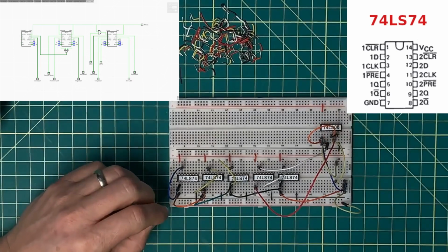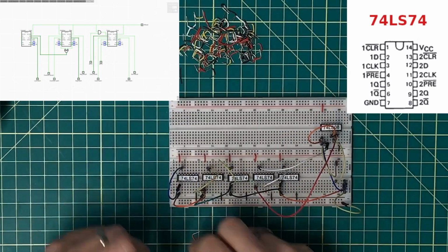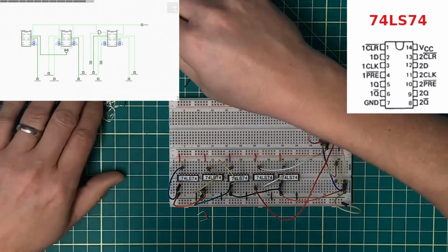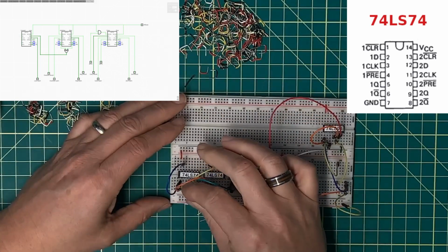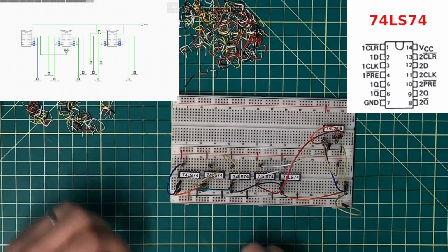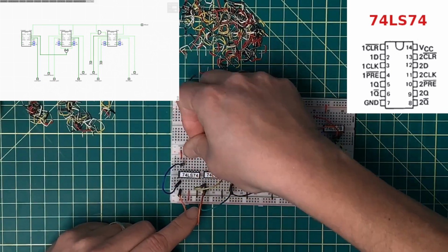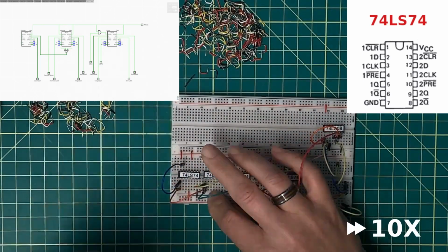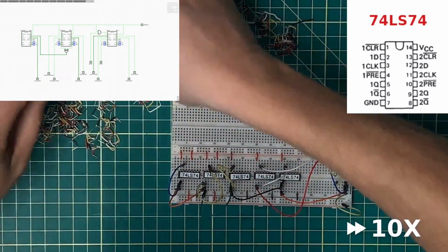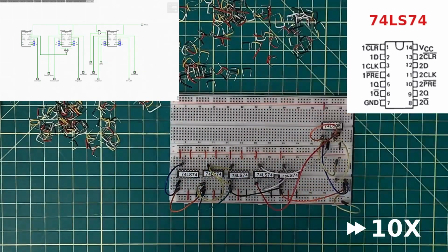Sets are all going to be tied. Let's see, that's pin 4 and pin 10. These are all going to be tied high. And I need some longer wires here. So pin 4 and pin 10. And so the key with the sets here, with the exception of the carry, is that it'll never actually directly be turned on or set.